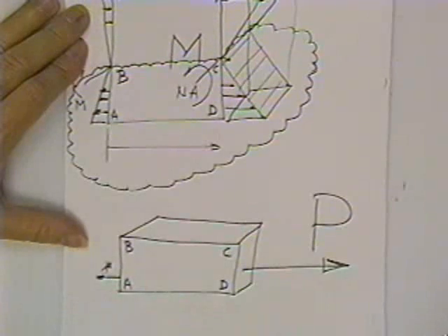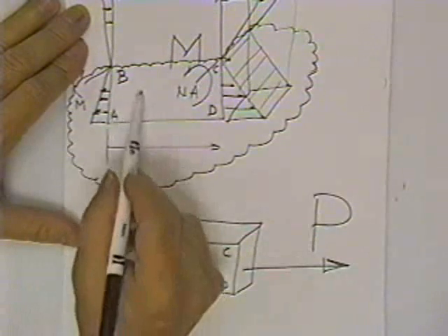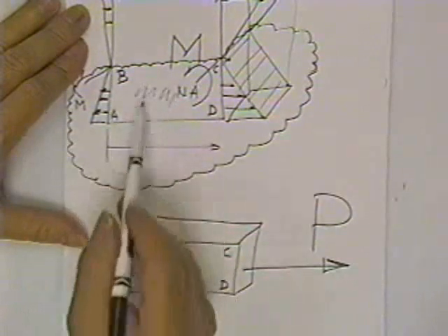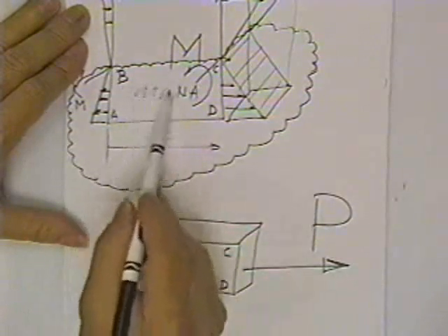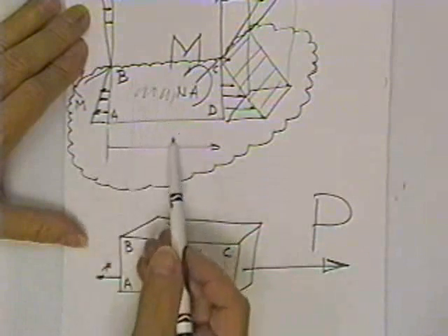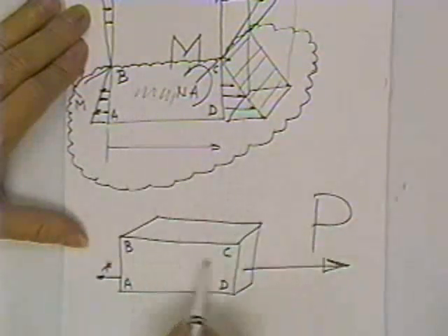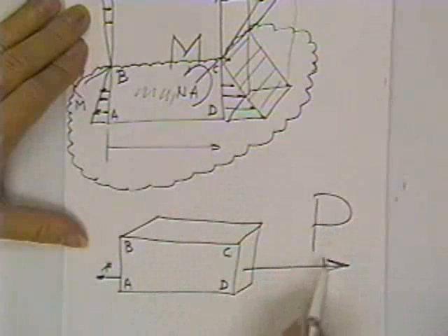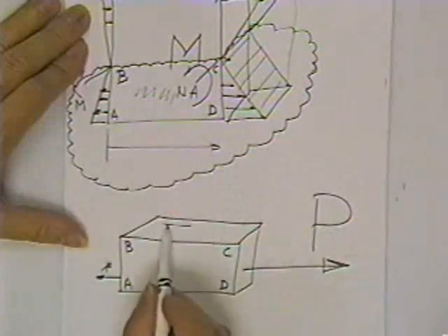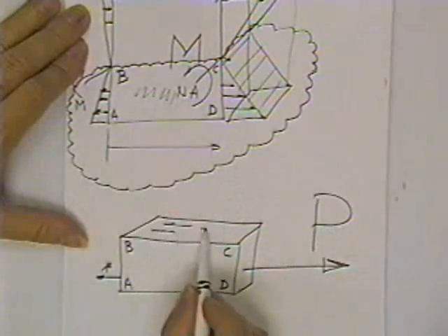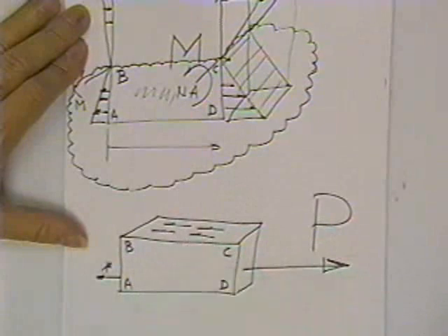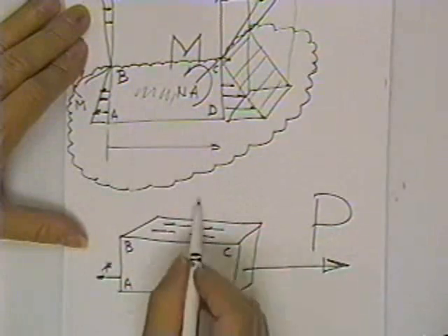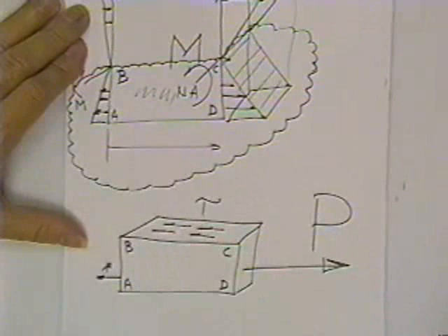And he says, that little piece is not in equilibrium. And we said, well, wait a minute. Maybe there's some stresses out in here. He says, I don't think so. There's nothing in there but air. Nothing on the bottom but air. Nothing on the back side but air. The only way this force here can be resisted is if you have some shearing stresses like this. And that's where those shearing stresses come from.